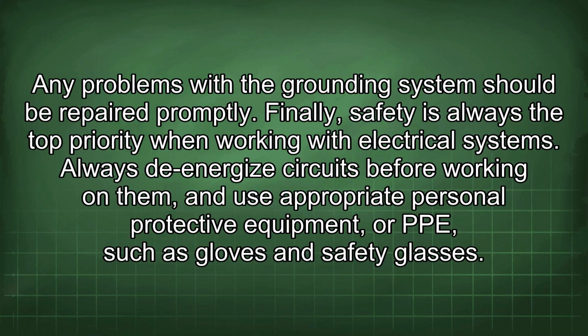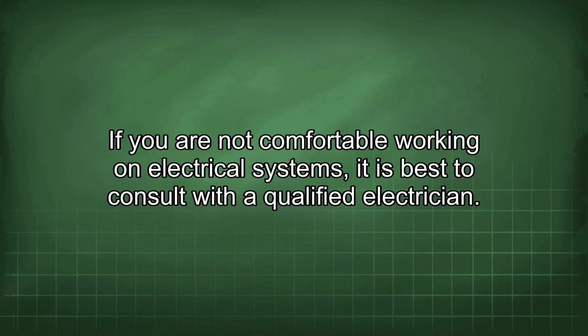Finally, safety is always the top priority when working with electrical systems. Always de-energize circuits before working on them and use appropriate personal protective equipment, or PPE, such as gloves and safety glasses. If you are not comfortable working on electrical systems, it is best to consult with a qualified electrician.